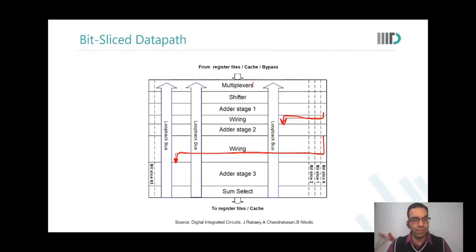Means if we give serial input and we take parallel output, so anything like that? A shifter is a set of flip-flops. So in those terms, you can think of using them as a scan chain also. Yes, no problem with that. But barrel shifters are not just for pipeline. Barrel shifters could be a part of, say, multiplication and division also.